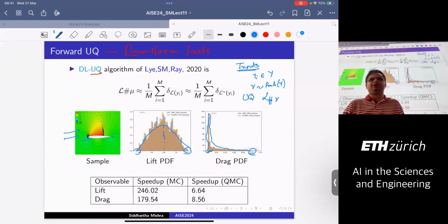If the drag is 0.1 and the lift is 0.4, the lift to drag ratio is 4, and no object will fly. You need a lift to drag ratio of approximately 100 or something to fly. But this can happen, right? If there are some extreme flow conditions, then you cannot do anything about that. So the idea is to propagate this uncertainty.